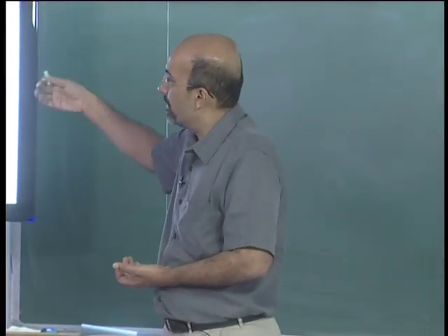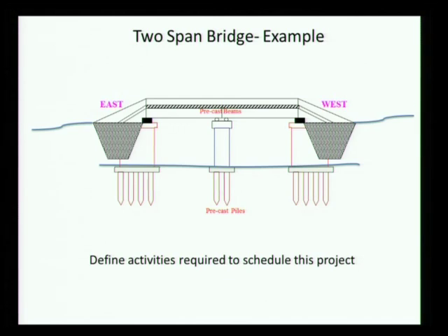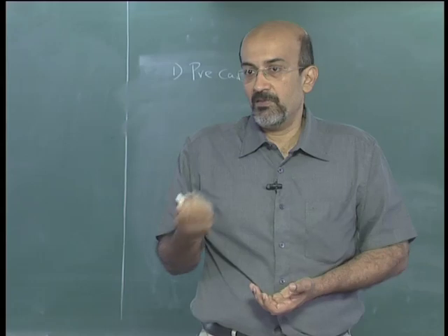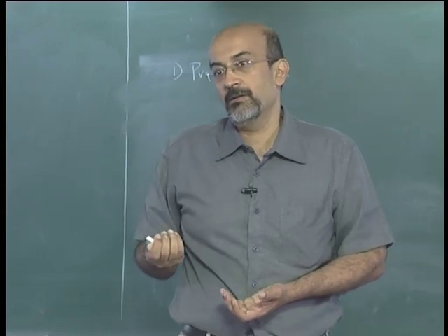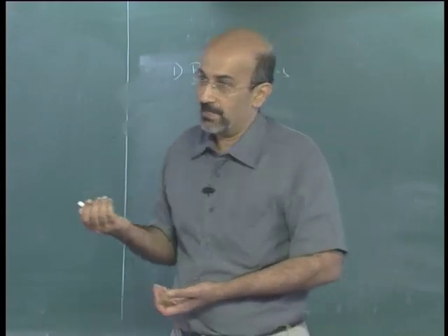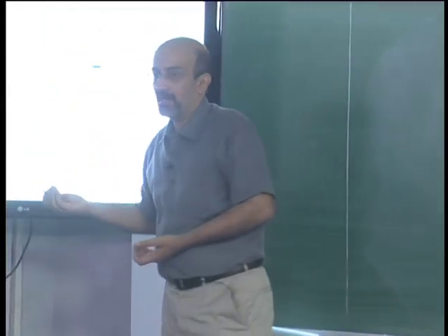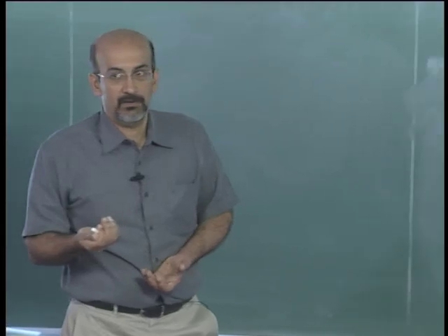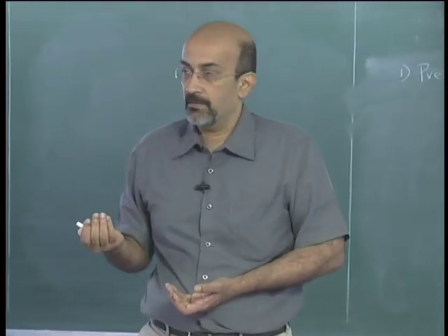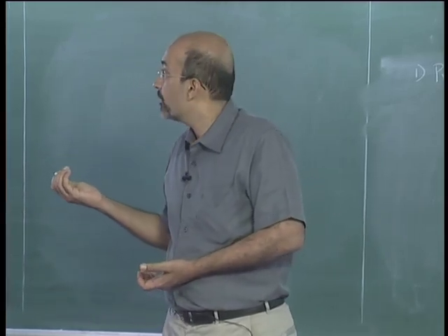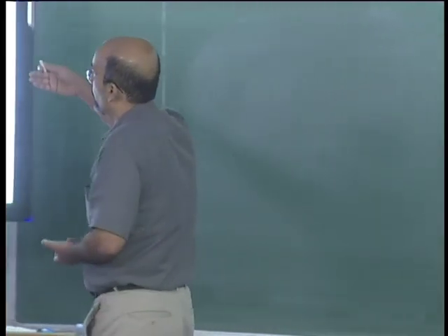Look at the structure. Now my piles are precast, my beams are precast. What are my other options? Let us go into the methodology. I precast the piles. Now what do I have to do with the piles? I have to drive the piles. After I drive them, I have to construct the pile cap. There is some sequence coming in here. After the pile cap, I have to think of the abutment and the piers. After that, the beams, and then there is a deck slab and the road over it.